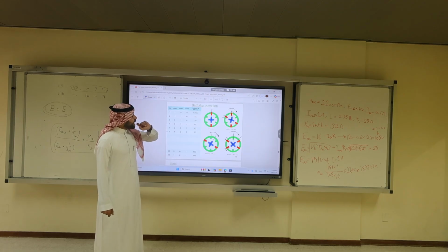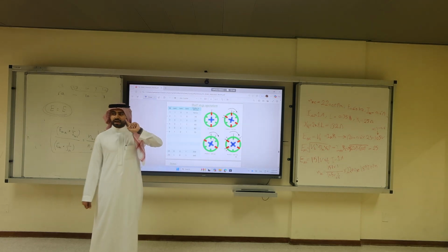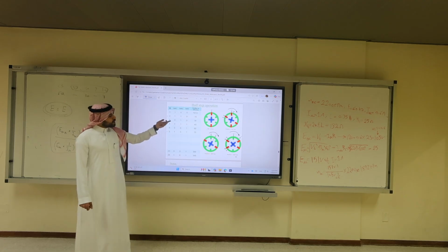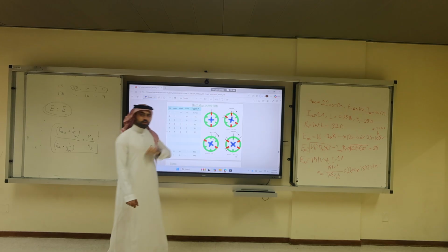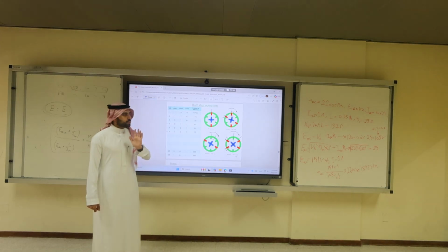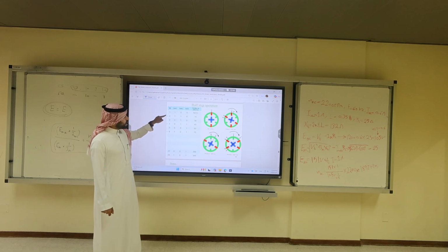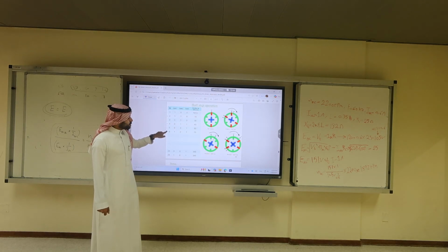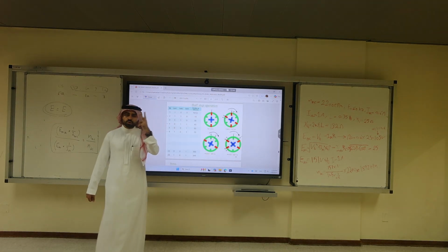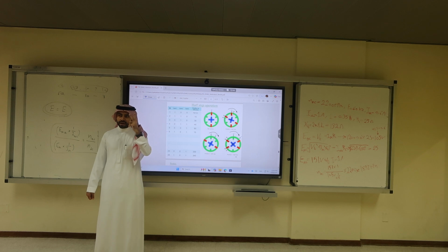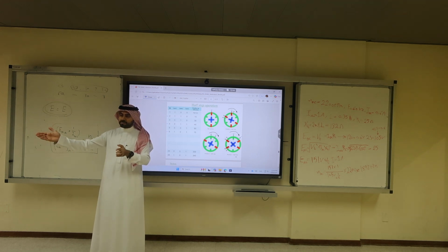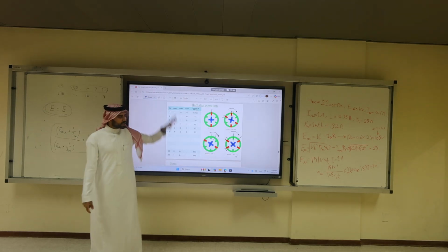Let me ask you a technical question. What if I make it always 2 coils on? This is a conceptual question. I skip the odd ones 1, 3, and 5. So I start here with 2, then 2, then 2. Now I'm having 2 windings active all the time. I will go back to full step, but I will have very high current. So this is one different operation that's not mentioned.